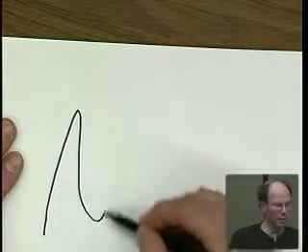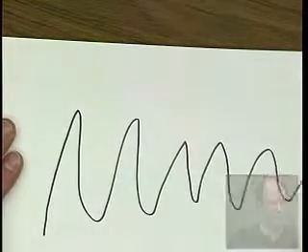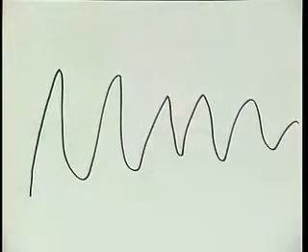Okay, so what do you do? Well, you get rid of the air, put this in a vacuum. Fine. But now you have a totally underdamped system, right? If now an earthquake happens, then the thing is going to respond to the earthquake, but then it's going to ring like this forever. Totally impractical system. You've gotten rid of this noise problem due to the air molecules, but you now have a system that, well, you can't use anymore.